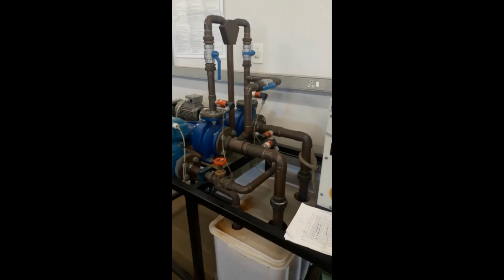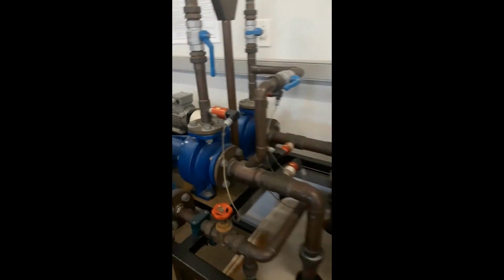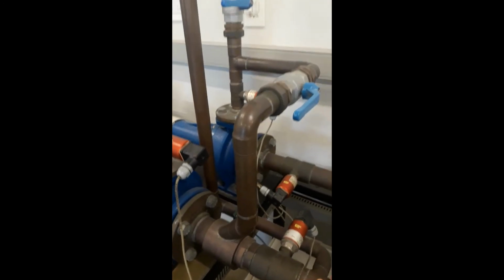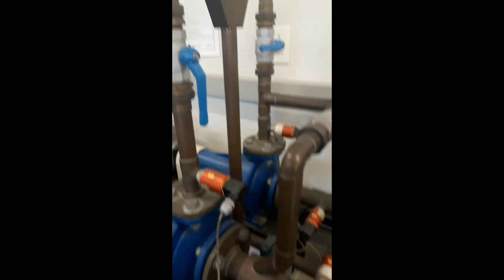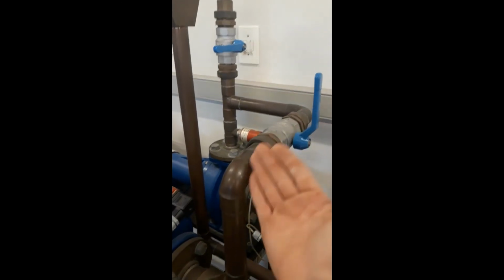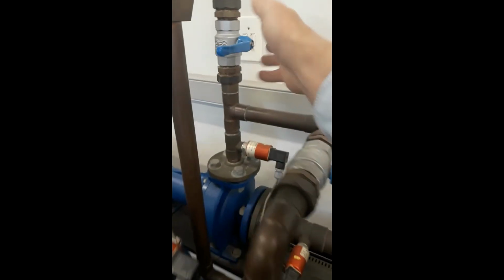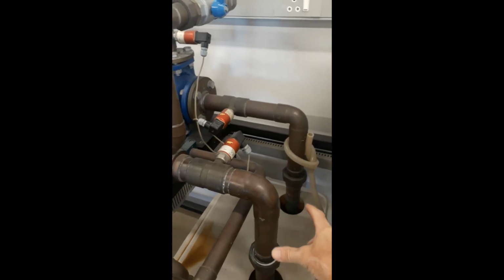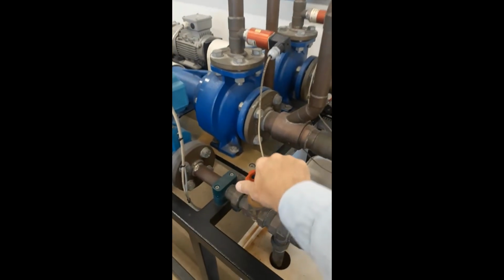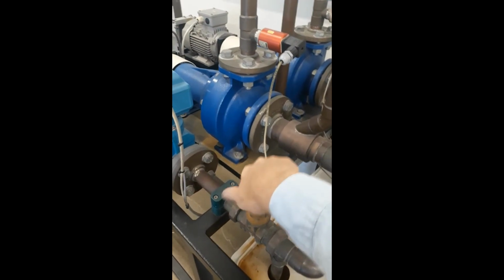For our pumps in parallel, we need to connect our pumps in parallel, of course, which means both pump 1 and pump 2 must deliver to the same delivery line. So we want to close the interconnection line, so pump 1 can't deliver water to pump 2 anymore. And we want to open the delivery for pump number 1 and open the delivery for pump number 2. In this case, both pumps suck water from the reservoir and they both deliver to the delivery line. And then again, to start, we want to make sure our control valve is fully open.